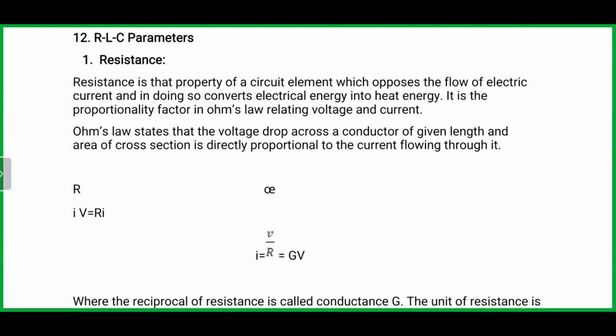You see, you'll be there and lightning... How come lightning can pass into your wiring and damage your gadgets? You understand it? Because you don't have a good earthing system, and you don't have a lightning arrestor. So when you have a good earthing system and a lightning arrestor, and the amps of your incomer or the RCB or MCCB or something like that is higher, are you safe? Yes, you are safe, because the lightning arrestor will arrest the lightning straight into the ground.